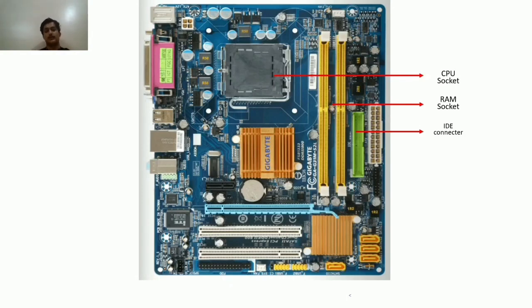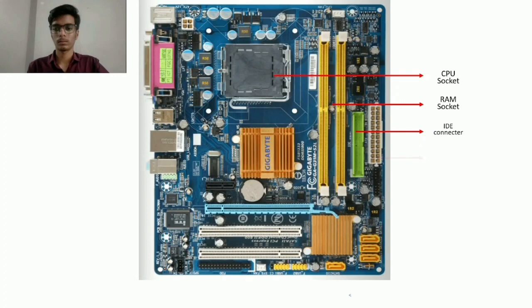The two most commonly used types of IDE cable are the 34-pin cable, used for floppy drives, and the 40-pin cable, used for hard drives. IDE ribbon cables have three connection points. One end of the IDE cable connects to the motherboard, and the other two are open for devices, meaning you could use an IDE cable to attach two hard drives to the computer.